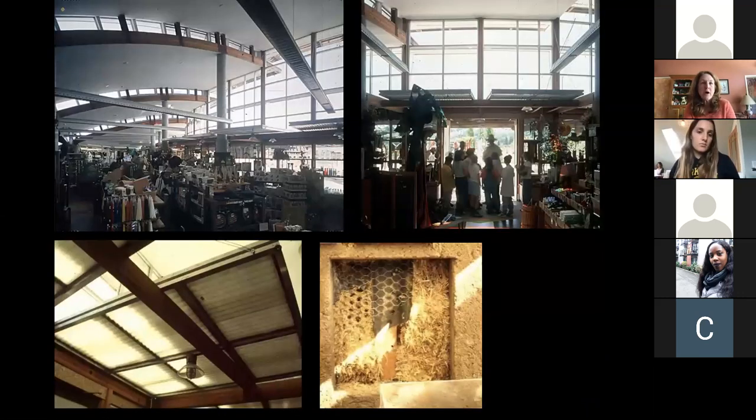But let me show you on the inside, this upper left. I said to look at how the roof was stepped down. Every time the roof stepped down, that vertical distance was glazed, and it's a wonderful way to bring in daylight and wash the ceiling with daylight. Those are also operable, so it allows for stack ventilation. You can see here these large windows and these panels that come down.